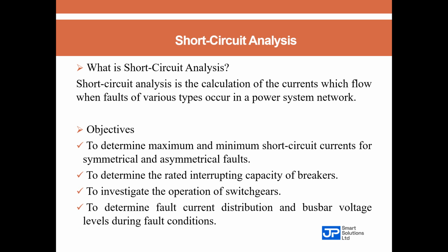Now, imagine you installed a breaker rated for 25 kiloamps, but then the real fault current is at 35 kiloamps. What do you think will happen? Of course, the breaker will blow apart. The equipment will burn. People will get injured. And guess the first question that will be asked during the root cause analysis investigation.